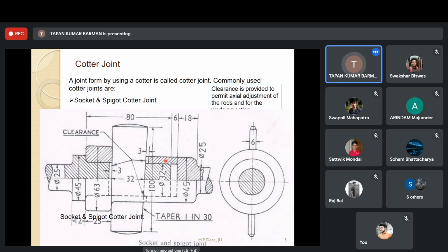For this component also, the right hand side component, we have restricted the hatch lines up to this. Also you see, here also we have put the hatch lines. Why? Because we do not know the exact length of this extended rod. The extension of this rod is there, but we do not want to show the full length because we do not know its dimension, but we want to represent that rod here, and for that purpose we have cut this object up to this only. We have shown the component up to this or up to this.